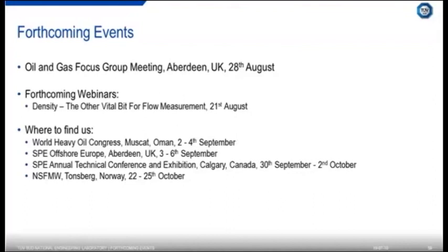So it might be 0.1% in the field. We'll test at 3 to 5%, and up to about 10-15%, you can effectively accelerate the erosion and then scale it back to determine the lifetime of an asset in the field. Once you get above 10-15% sand concentration, you start to get particle-to-particle interactions, and you can actually get less erosion than you might expect. But as long as you don't go above 10-15%, then you can effectively accelerate the wear and predict field life.